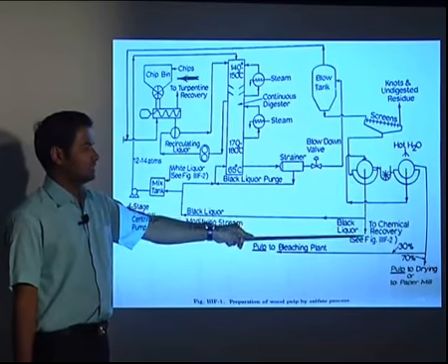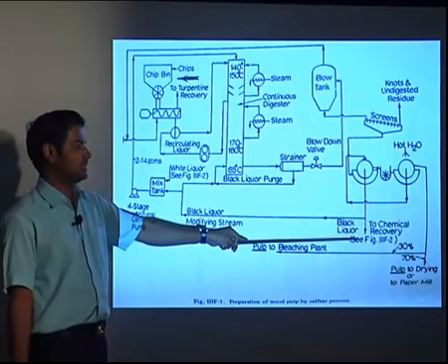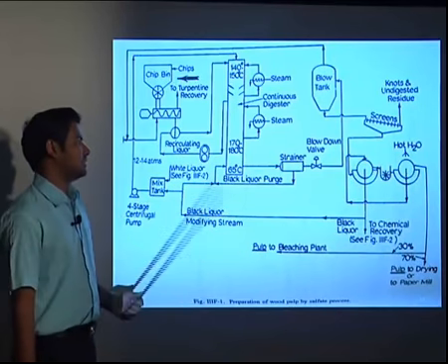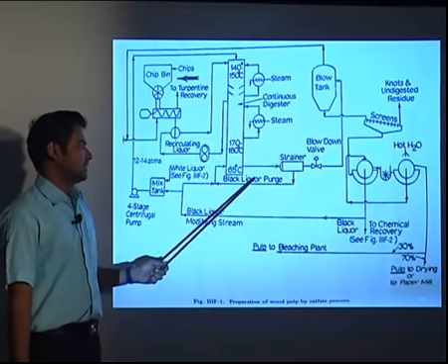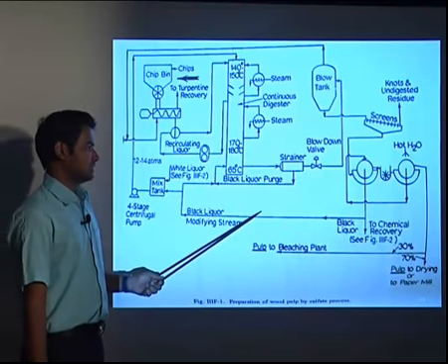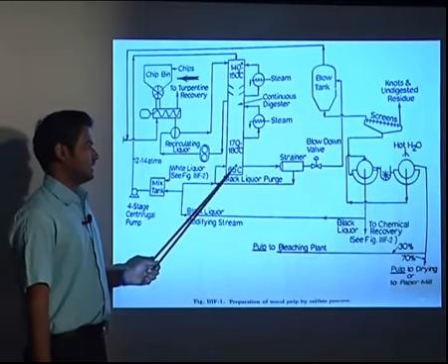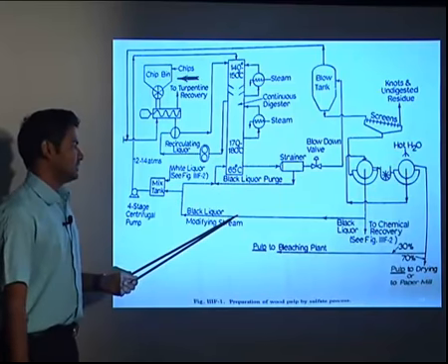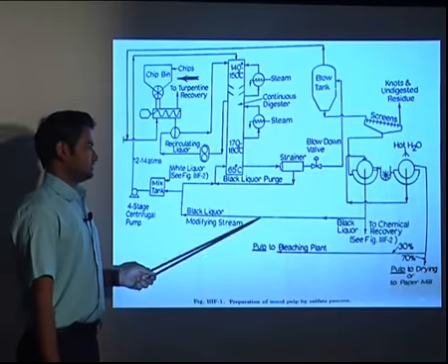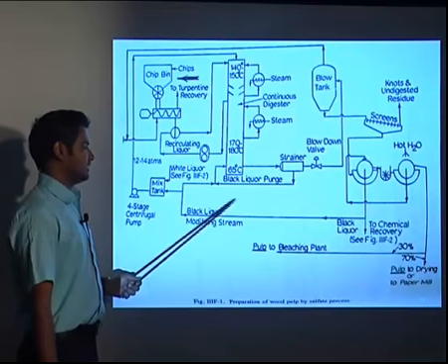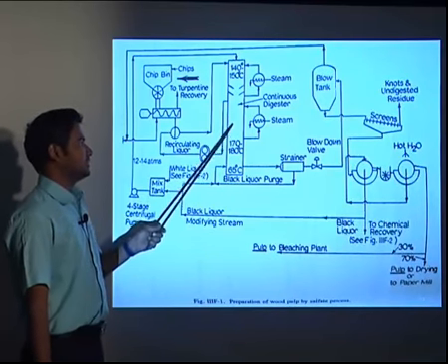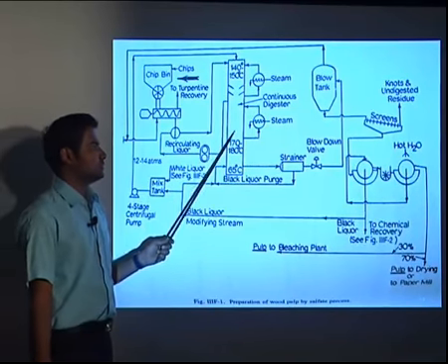Whereas the filtrate which contains the chemicals, we send to chemical recovery. The lignin-containing part will be named black liquor. It will be recirculated in order to maintain temperature. Also it contains the chemicals and is heated, so we can send it to the digester again to make the wood soft again.